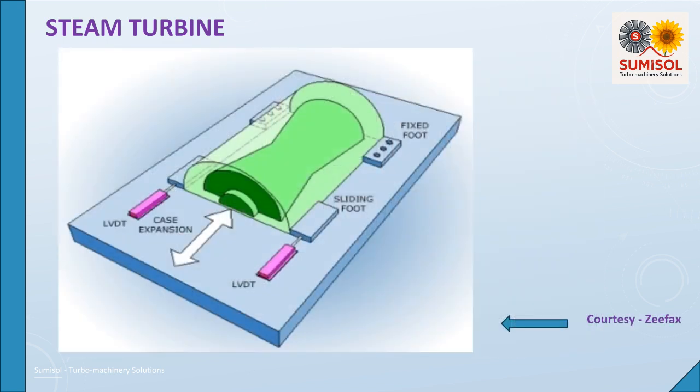In large turbomachinery, the thrust bearing assembly is usually located either inside the front standard or between the HP/IP turbine and the first of the LP turbines, and it is intended to control the axial movement of the rotating shaft relative to the stationary case, as it warms up during startup periods. In this arrangement, the front standard is usually permitted to move axially to accommodate the thermal expansion in the other direction from the HP/IP turbine sections, but it is restrained from moving radially.